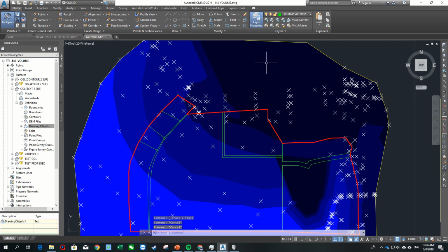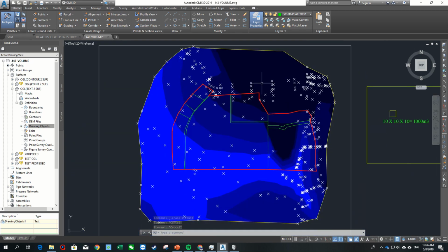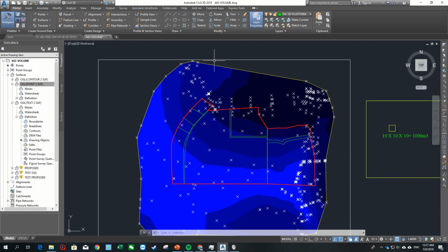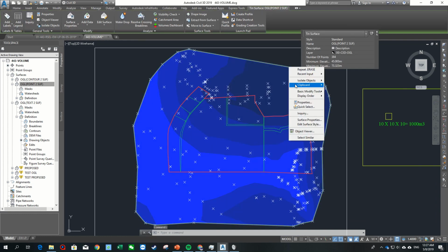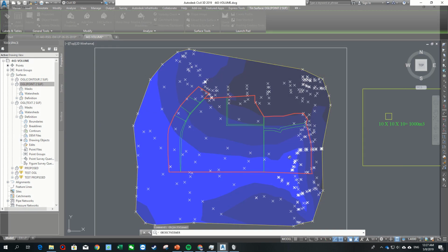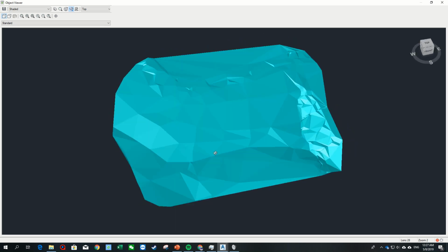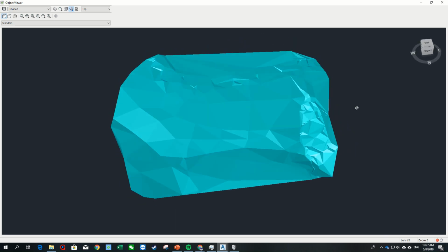Because these 2 points are interrelated with the surface, after I delete the things, the OGL point comes up with an error, which means it's different already. It's no worry, you just have to click rebuild, and then you click rebuild. Okay, now it will generate a new one. Now you can see again, is there any error come up? See, the platform become almost flat already. This is what we want.